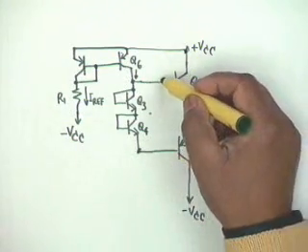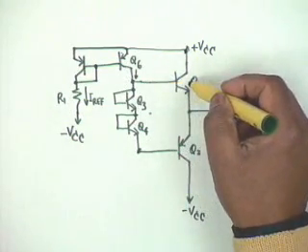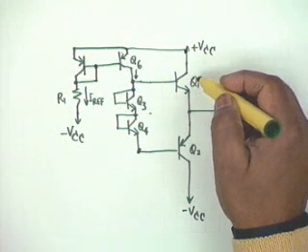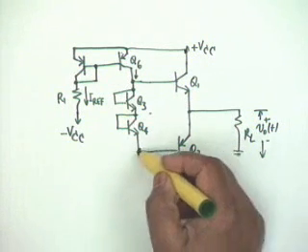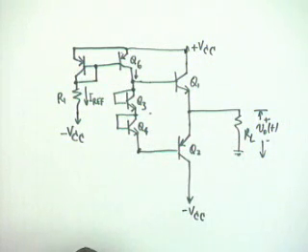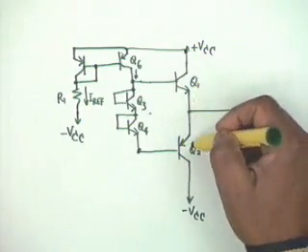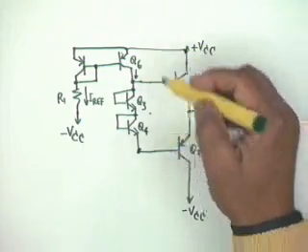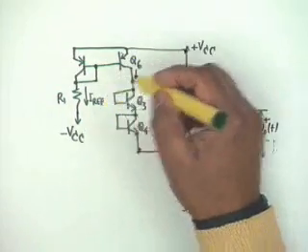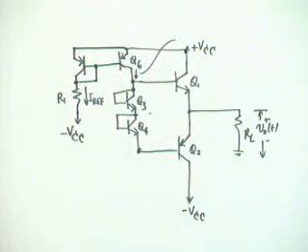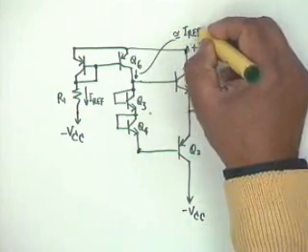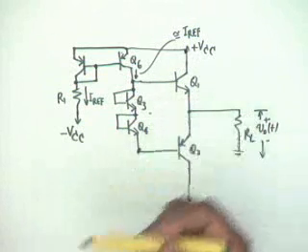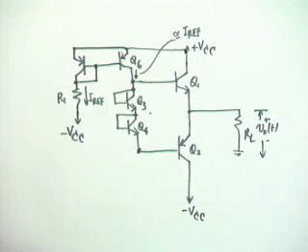Not just that, you see, it also supplies a current to Q1, IB1. It also takes a current from Q2, IB2. This base current goes away. Agreed? Nevertheless, if the two betas are large, then we can ignore these two currents. And as you know, in a current mirror, this current would be approximately IREF. Okay, approximately IREF. So the current that passes through Q3 and Q4 shall be approximately equal to IREF